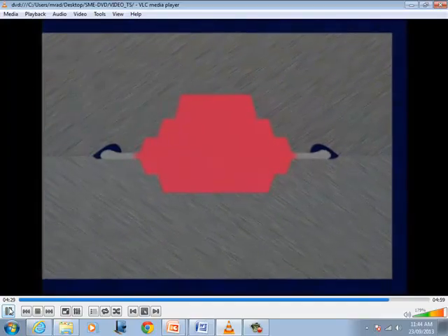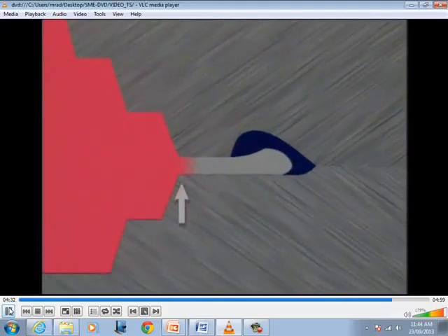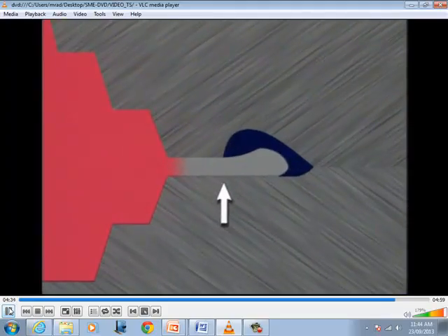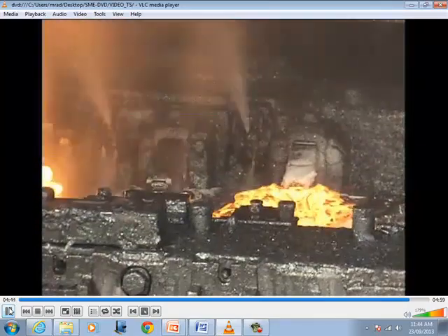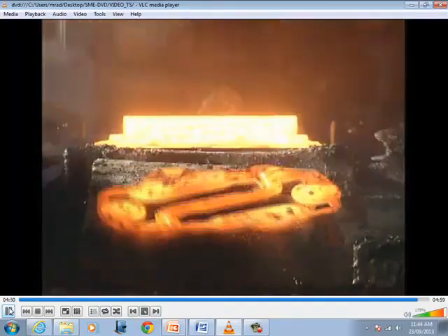Flash comprises a flat region called the land, and sometimes a bulbous region at the end of the land created by a gutter in the upper die. The thin flash cools rapidly, increasing pressure within the impression, which assists metal flow in the impression details. Once finish forging is complete, the flash is removed either manually or with trimming dies.